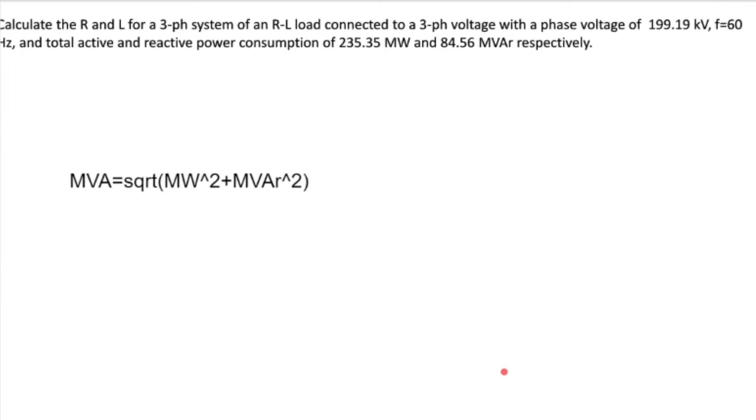Will you remember that in these cases, the power factor for each phase, we didn't talk about that. We talked about per phase active power, per phase reactive power, and so on. We did not talk about per phase power factor because that does not make sense. The reason is that the resistance and inductance are the same for each and every phase. So the per phase power factor will be the same.